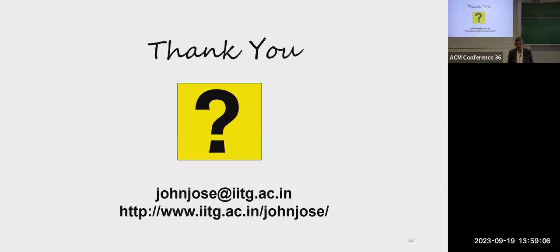I have a prefetch buffer. Yes, a separate buffer for prefetch. Does this technique work there? No, if I have a prefetch buffer, then you have to take a call whether you will keep it in the stale L2 or in the buffer, based on access time. If it's a small buffer, then the access time may be easy. Here it is like you have space, but the bigger the space, the indexing into the L2 cache will take slightly more time. So the advantage you get is storage versus access time, one cycle more. So we can use a combination of this. There can be a case where there is no stale block. Then you are not going to keep and prefetch it. Then a buffer will.